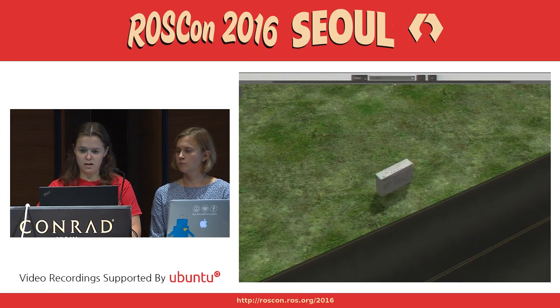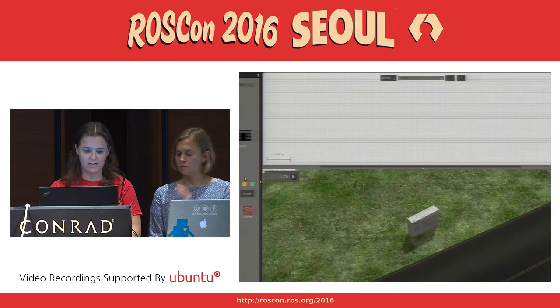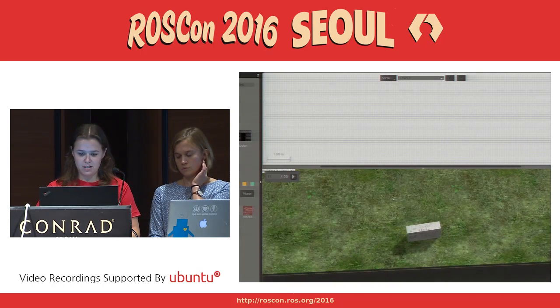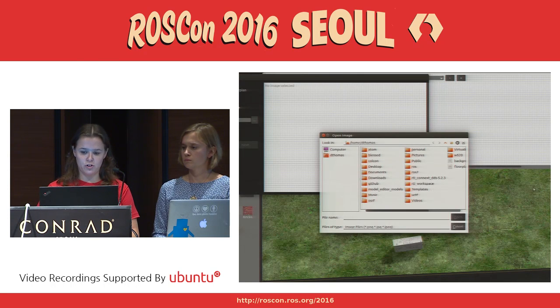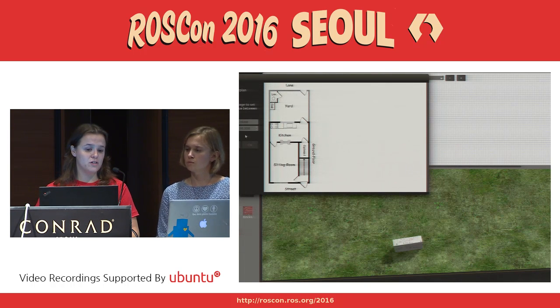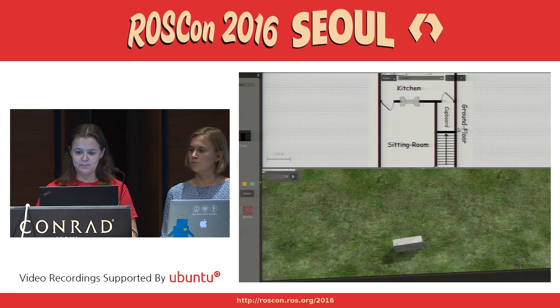So we have here on the top the 2D view of our building, and on the left here we have a palette with a lot of options for our building. The first thing that you can do in the building editor, which is really cool, is import a floor plan of an area that you already know and you just want to draw that. So we have a floor plan here of a little place. So we import it. If you know the resolution, you can just type it here. If you don't, you can kind of click on 2 points in the image and have a rough estimate. Oh, this is about 5 meters, and we scale the image for you.